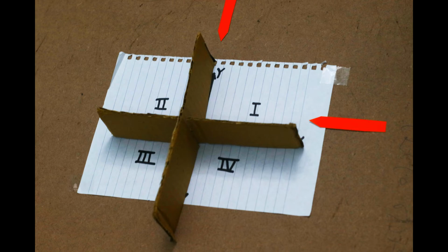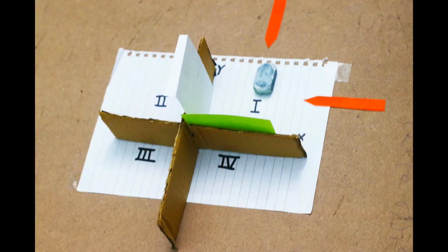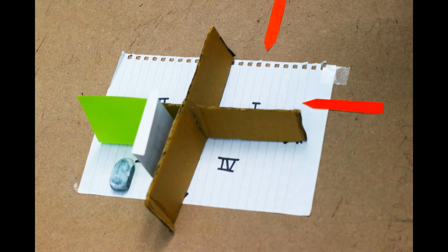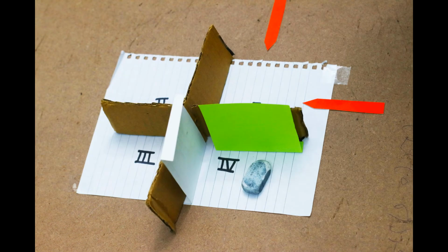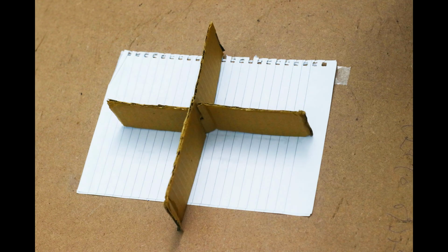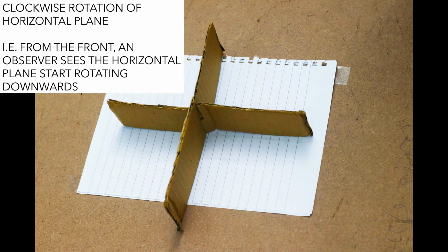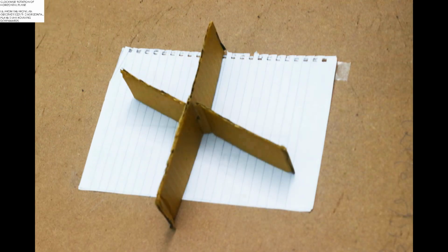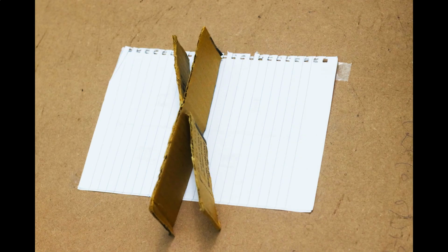As we have already seen, there can be four possible positions of an object located in space, and depending on its position in space, the positions of the front view and the top view will change. After we have recorded the front view and the top view of the object, what we need to do is convert this 3D representation into a 2D representation. To do that, we rotate the horizontal plane around the origin in such a manner that it now coincides with the vertical plane. In a 2D representation, the pivot line appears as a line and is denoted by xy.